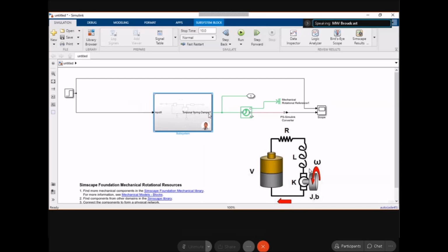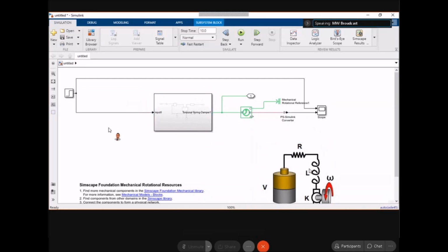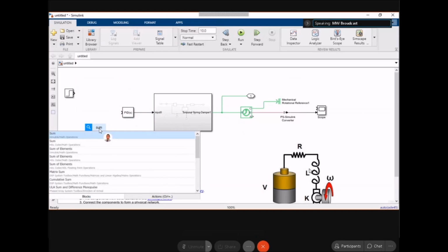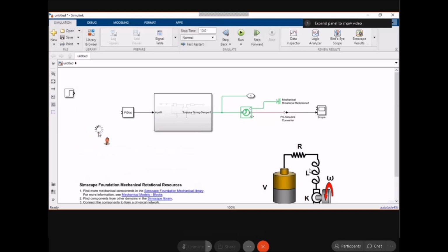All right, so by doing that, I know that I will need a PID controller, so I can just type PID. And I can delete some of these signals. And I know that the PID needs, as an input, the error from the actual motor speed that we're measuring and also a reference speed. So I'll do that right now. I can input the signs that I want here for this sum block. This way I get the error, and I can name signals. Let's call it motor speed.